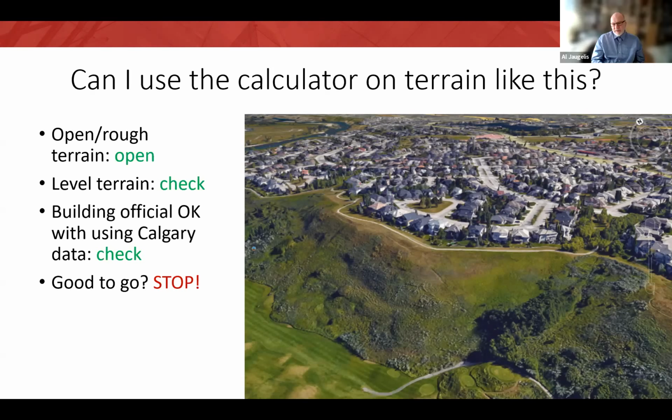So this development was built in the 80s, before the code addressed this kind of wind condition. Is that right? That is right. When the investigator talked to me, I explained how the code worked in the 80s and how it works today, and said that even today, if you were not cognizant of the wind speed up over hills and escarpments, and most users are not, selling into Part 9, where they consider all Part 9 buildings to be basically the same thing, you would still wind up with a similar result, not being cognizant of what we're presenting here today, Al.